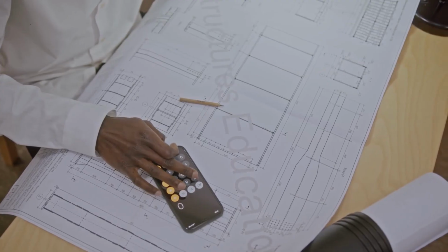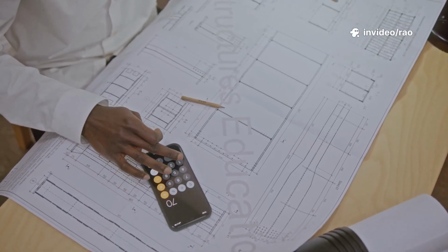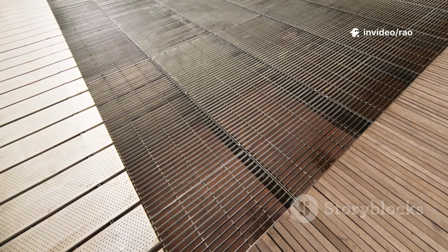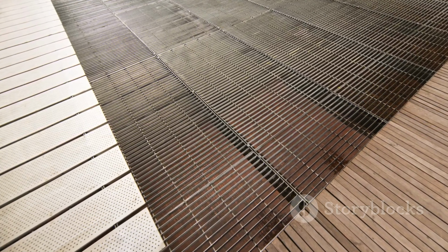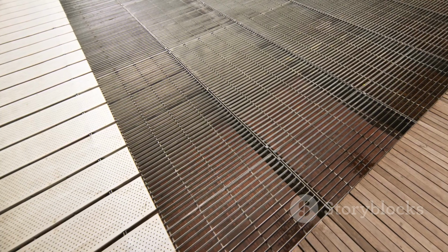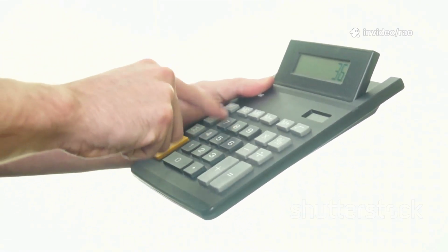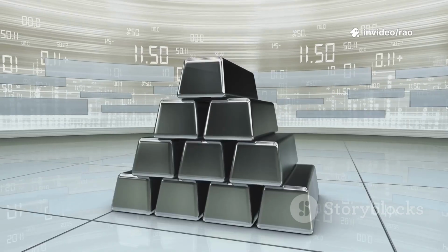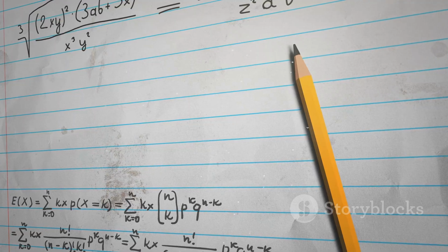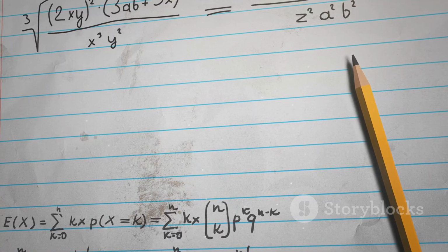This additional length must be added to the clear span of the bar to get the total cutting length. It is also important to note that for practical calculations, we often deduct the concrete cover from the slab span, but for this illustrative example, we are using the full span for simplicity. Now, we can calculate the cutting length for a single main bar. The main bars span the 4000 mm length of the slab. Cutting length per main bar equals span of main bar plus 2 times hook length.